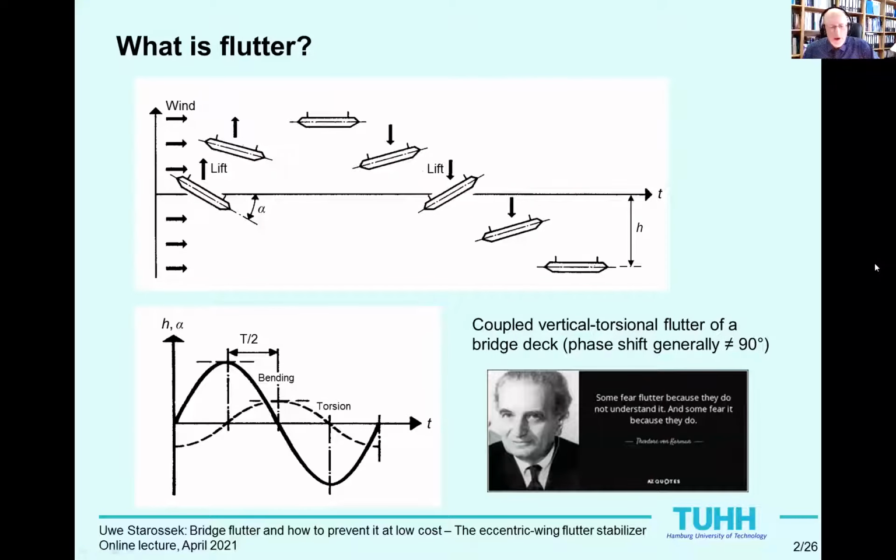Flutter is feared because it is a stability phenomenon, comparable to the buckling of a column or a plate. It occurs suddenly and possibly unexpectedly, and when it occurs, little can be done and the consequences can be disastrous.